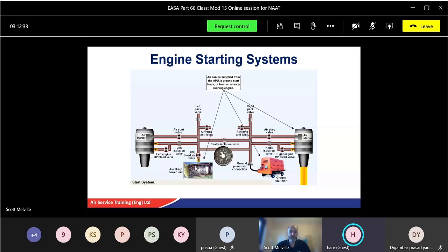LP cooling air outlet duct. Yeah, good, thank you. There'll be a temperature sensor, thermocouple, some sort of heat sensor, in the LP cooling outlet. There'll be normal temperature in there anyway, and that'll be monitored by a separate sensor. But if that gets too hot, and it shouldn't be getting too hot, then maybe something's cracked, maybe a turbine casing's cracked, or a pipe's cracked. It lets us know that in the cooling air, it's gotten too hot, something's wrong. Potentially stop a fire from happening.